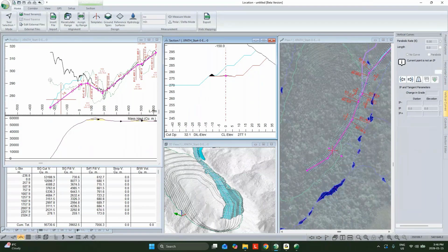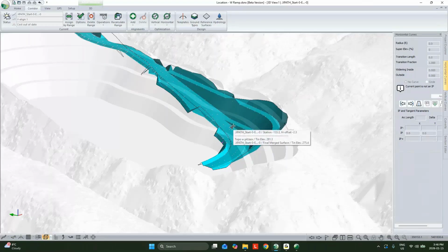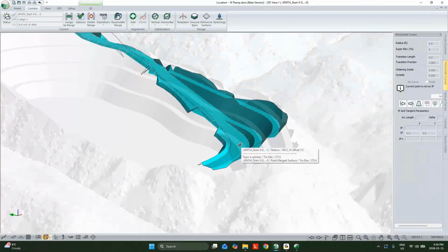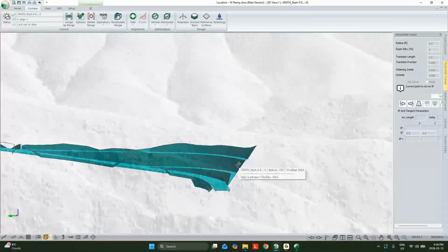But for the sake of time, I'm just going to switch over and we can see one where we've got our proper curves being defined and that benching being feathered in where the grade of the road is, well, near 8%, but our benches are flat and matching the elevation of the pit. And it's kind of a weird one to see, just with the orientation of things.